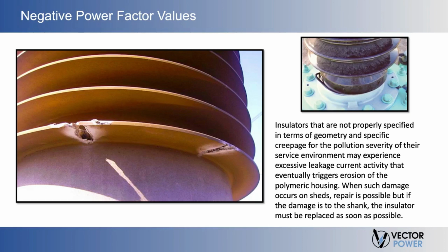The error is usually accentuated if tests are made under unfavorable weather conditions, especially a high relative humidity, which increases the surface leakage. There appears to be no clear-cut way of knowing whether an error is significant or what remedies should be taken to overcome an error. A frequency sweep may give additional information. The best advice is to avoid making measurements on equipment in locations where negative dissipation factors are known to present a problem when unfavorable weather conditions exist, especially high relative humidity.